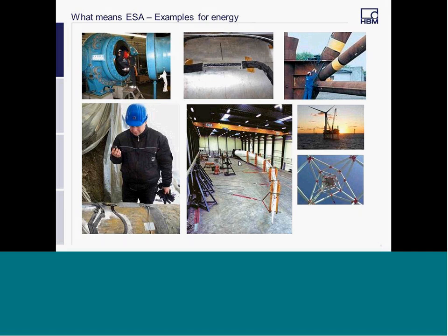That's really impressive. The only thing you always have in mind is, please don't break now when I'm beside. Or here the construction of that offshore platform, also to generate wind energy. That's quite difficult to measure, because you can imagine it is under the sea, a lot of salt water, not a nice condition for a strain gauge. But we have a lot of experience here, so we can offer you a solution to apply strain gauges even underwater.